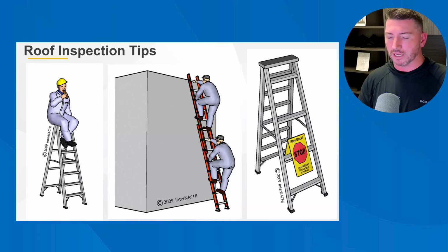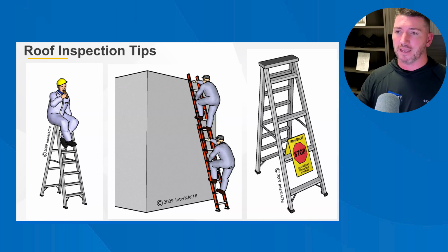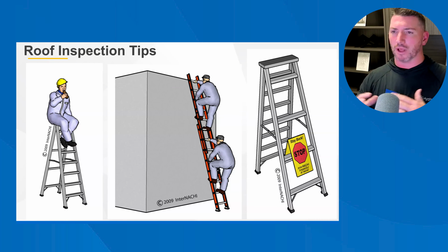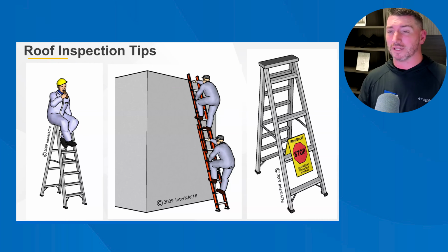So definitely hone in on flashings, roof appurtenances like heat vents, power vents, attic fans, box vents, turbine vents. There's many, many more: skylights, solar panels. If you have a very simple up and over roof, there's hardly anything coming out of there in terms of protrusions, and you just have an up and over gable roof that's shingled on both sides. That's a roof that's very seldom going to have a serious issue.